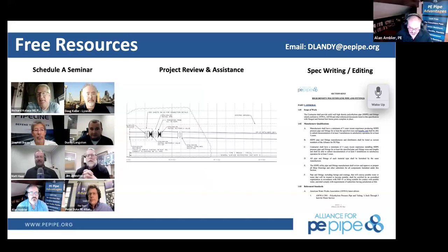All right, Pete, I'd love to tell you about it. We certainly updated it with additional testing measures. That is going to be pressure testing, fairly detailed from ASTM, also the guided side bend back test and how to execute those and when to execute those. And then we have the robust set of open cut construction, embedment, backfill, horizontal directional drill, slip lining, compressive fit slip lining, pipe bursting, both for potable water and for sewer, and they're all broken out as PDFs and Word documents, Pete.